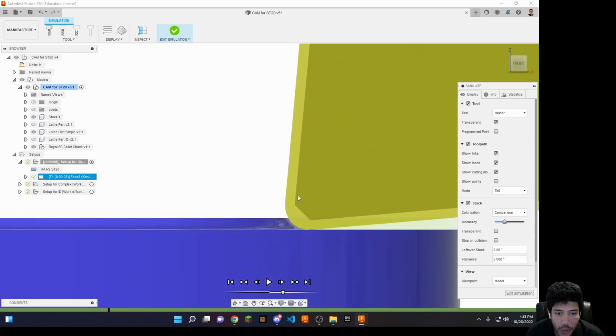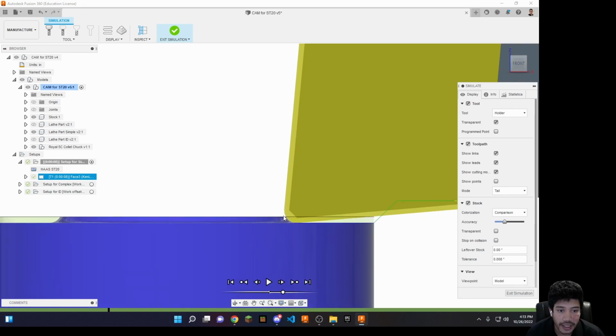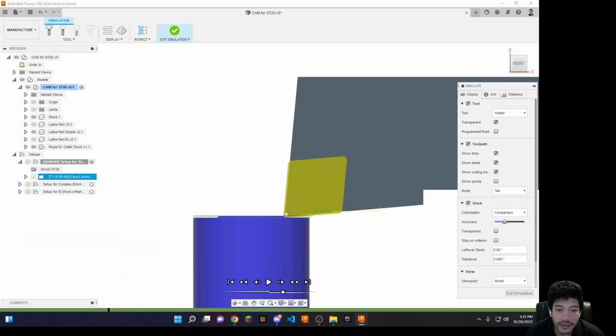Okay, so what it's saying is take this corner radius and only use less than 90% of it. So it will never be able to get onto this edge, because the rule that we have specified for step over is take the corner radius and use only 90% the depth. And this will ensure that we can face correctly.